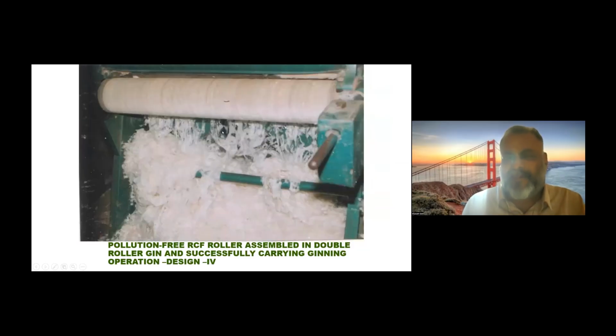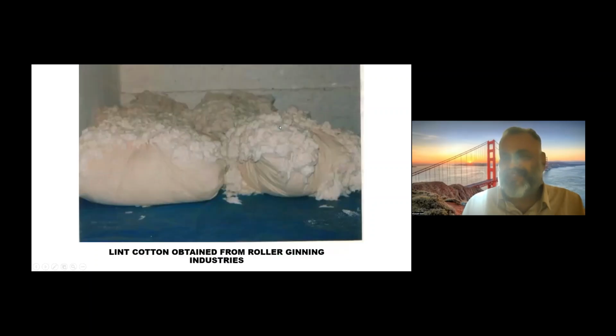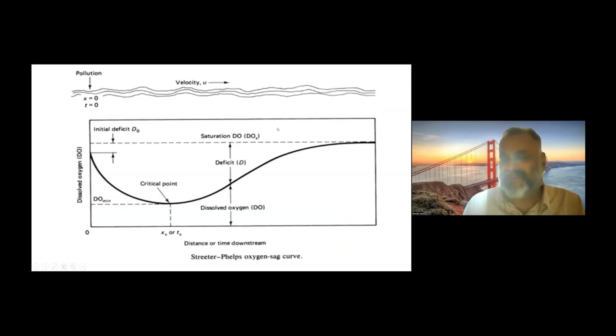So this is a ginning machine that is separating the cotton fiber and seed. There are double roller ginning machines and single roller ginning machines. In 1920, the ginning machines were developed. The roller material which was used is called leather clad rollers, chrome composite leather clad roller.